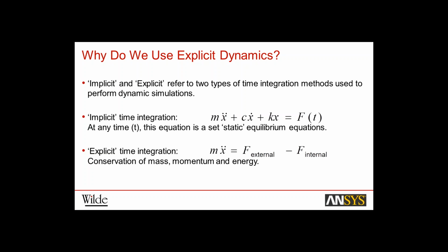In terms of explicit time integration, here we're using a different approach where we're applying principles of conservation of mass, momentum and energy. So where we apply our load, we're applying these principles to our structures and working out forces within our elements. Once we've got the forces, we can then calculate the accelerations and then integrate the accelerations to calculate velocities and displacements. We can update our mesh and repeat the process and look at the solution as it progresses, as time increases.